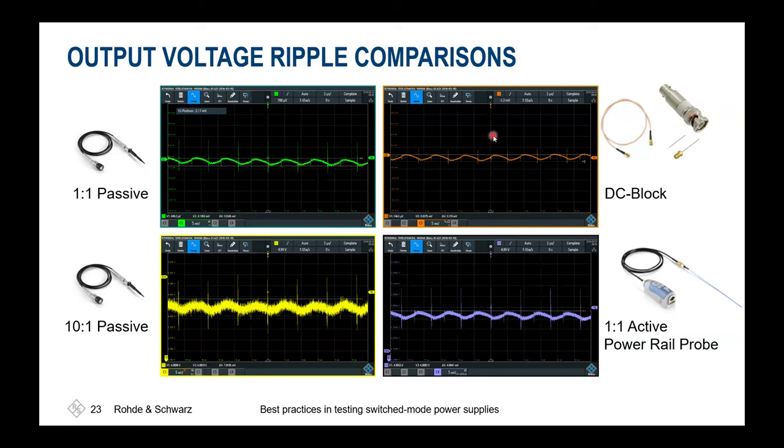Typically for oscilloscopes, the internal AC coupling is not specified, so you'll have no chance without using an external signal generator, performing a sweep, seeing when the sine wave you're entering there gives you the full amplitude again. But that would be additional effort. That's why typically we do not recommend to use DC blocks if they can be avoided.